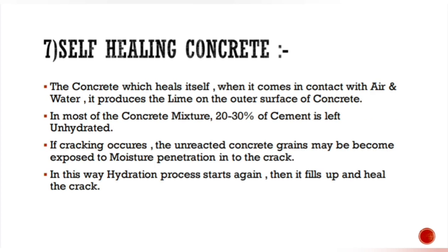Seventh, self-healing concrete. The concrete which heals itself is known as self-healing concrete. In the concrete mixture, mostly 20 to 30% of the cement is left unhydrated. In future, if a crack forms, the unhydrated grains come in contact with moisture, and again the hydration process starts. It automatically fills up the cracks. Due to this nature, this concrete is named self-healing concrete.